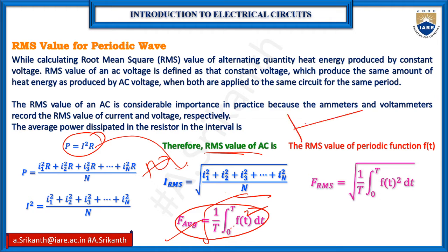This is my sine wave, and at this point I want to measure the supply. When I check the supply at different timings, in your multimeter we'll get positive 230 to negative 230. So it's varying, not a fixed value. DC means it's a fixed value, but AC means it's alternating. Alternating means we can't say at which timing the value is there.